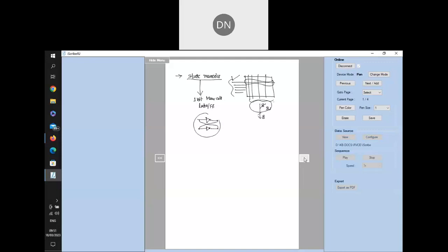This type of arrangement is capable of storing 1 bit of information even when the data is removed from the inputs. If this contains 1 and this contains 0, this state will be held in this bistable latch as long as power is applied. If you drive the inputs to the new state 0 and 1, even though you remove the inputs, it still holds the data. This is the principle behind holding 1 bit of information in any static memory.